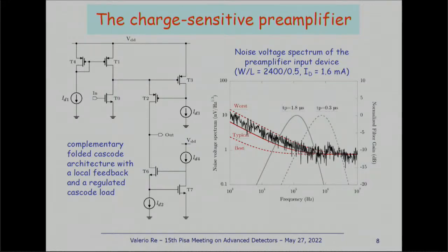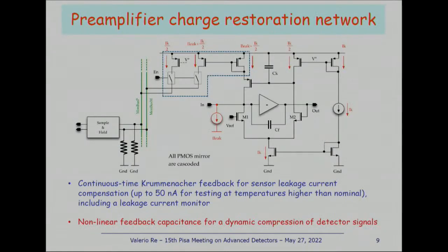Actually, it's interesting that we measured a relatively higher 1/f noise with respect to the typical simulation models. And so this gave us some excess noise that we measured on the full chip. Anyway, we are still able to stay inside the specifications.